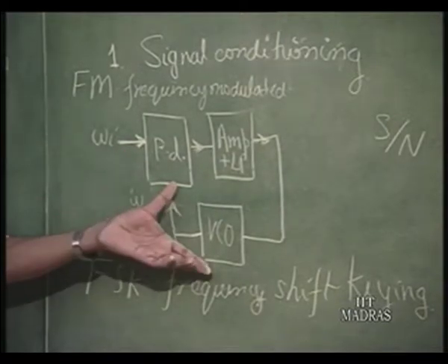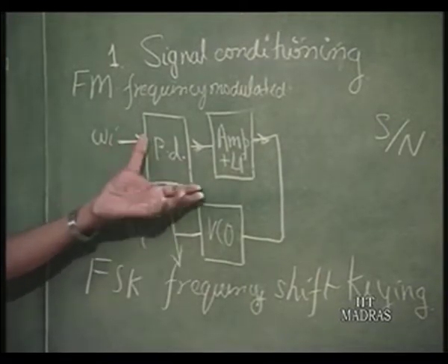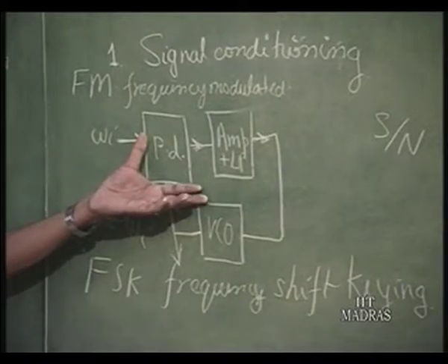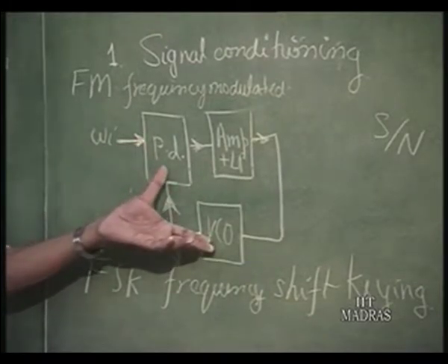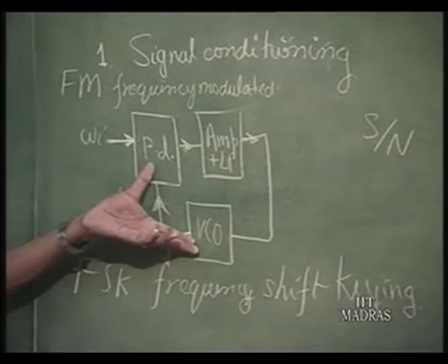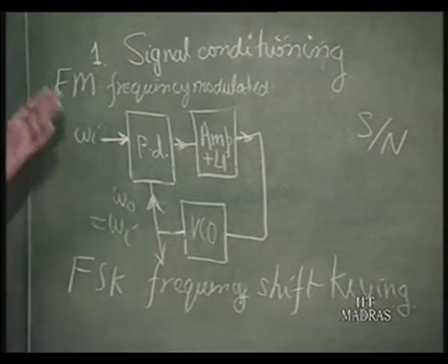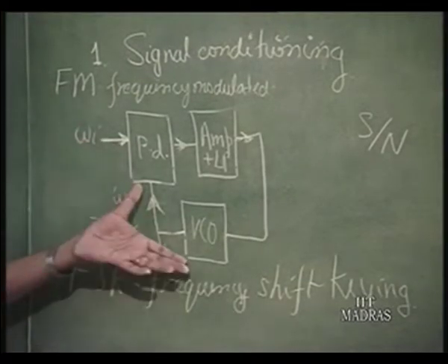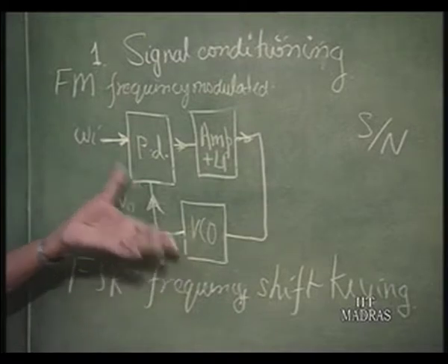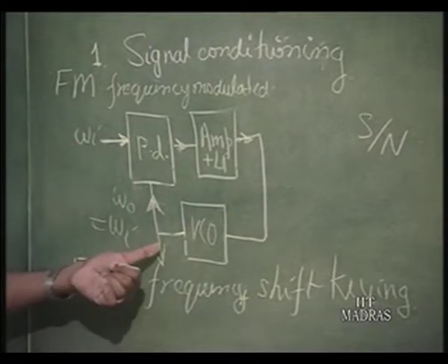Correspondingly, the VCO should be free running either at the horizontal synchronization frequency or the vertical synchronization frequency. This is another way to get rid of, okay, noise. The other part of the signal is called noise for this particular circuit. So, signal to noise ratio improvement has occurred drastically here.